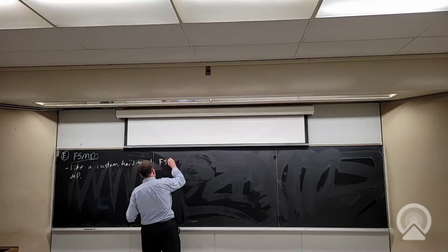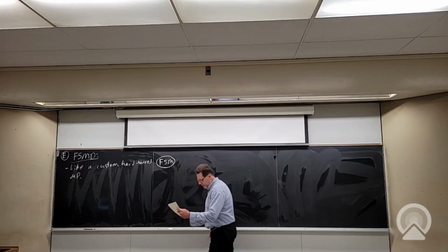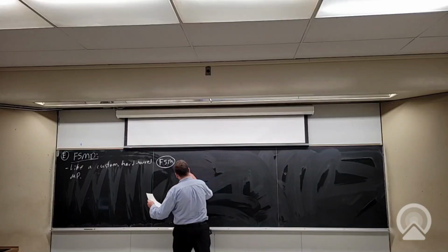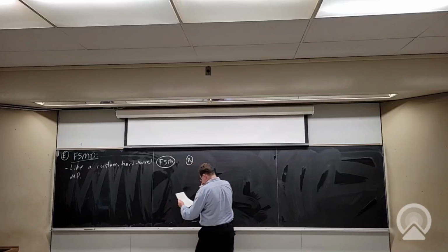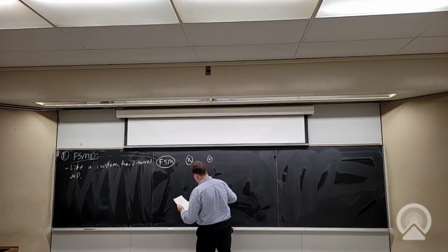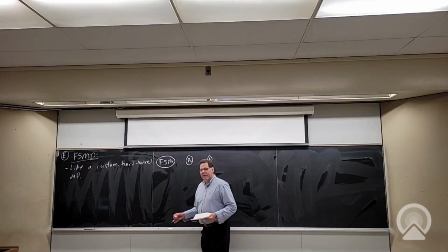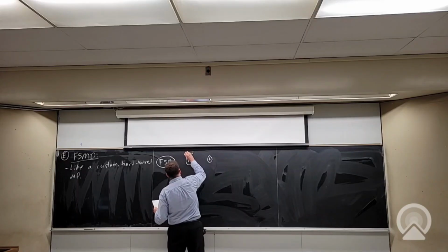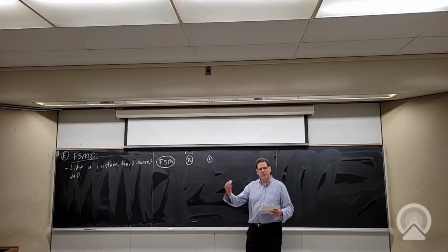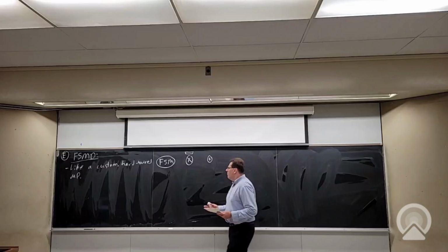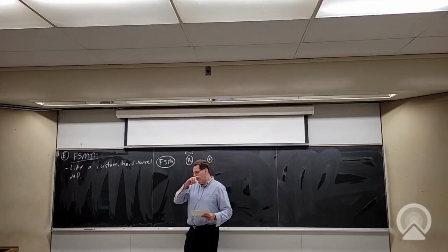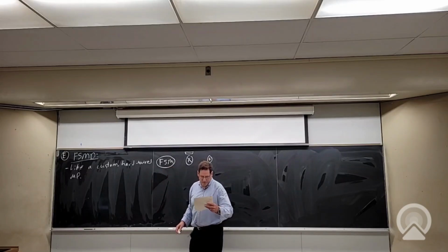So you build a finite state machine. It'll go through some sequence of states, and that state machine is controlling a data path. So you choose what data path you want. Maybe I need a multiplier and an adder, because I'm doing that quadratic equation again, say. And I'm going to need usually some muxing. The whole point of this style is that I want to reuse a data path, just like a processor does. But maybe my sequence of what I'm going to do with it is pretty repetitive, so I don't really need to define instructions and a decoder and so on. I'm just going to directly control it with a finite state machine.